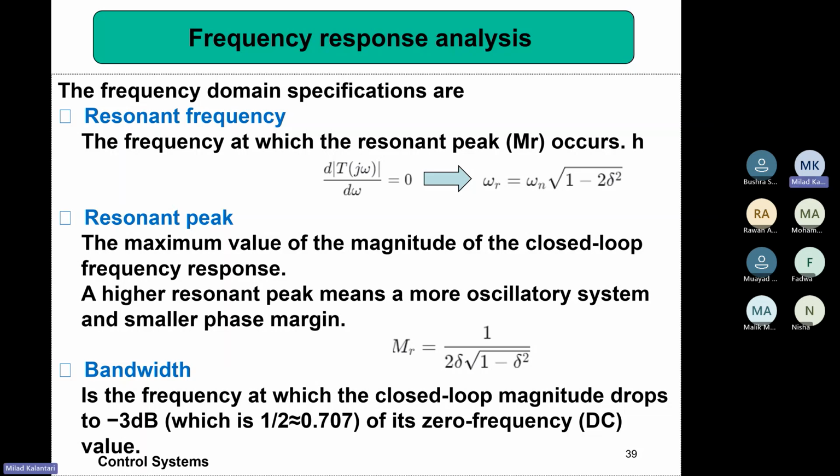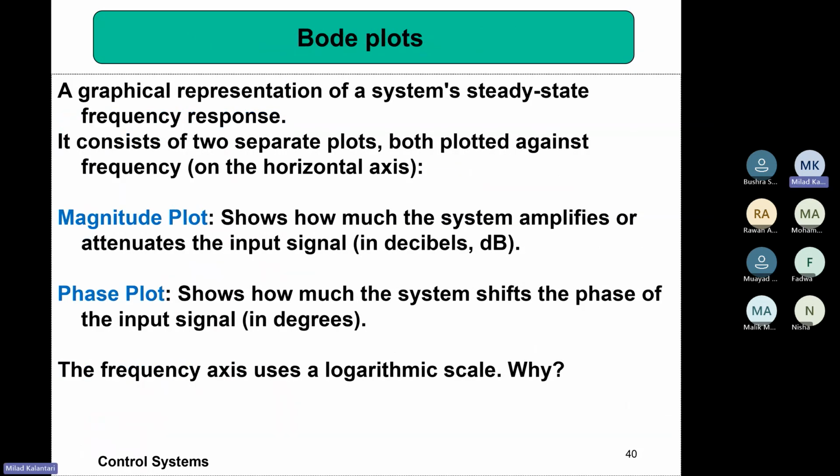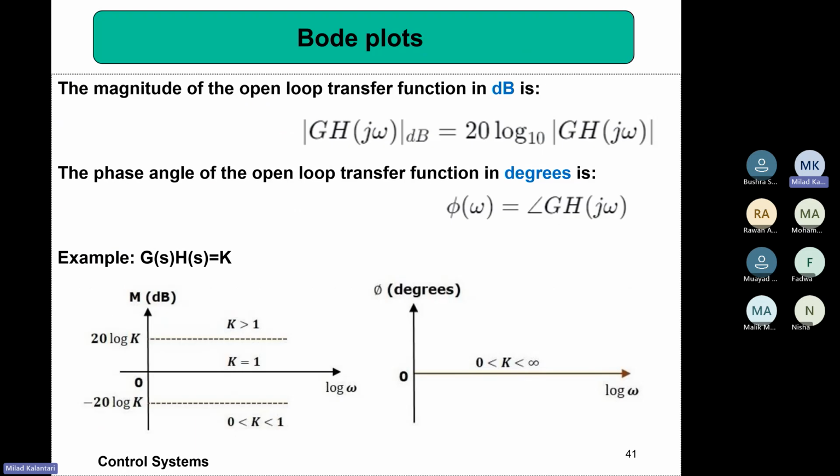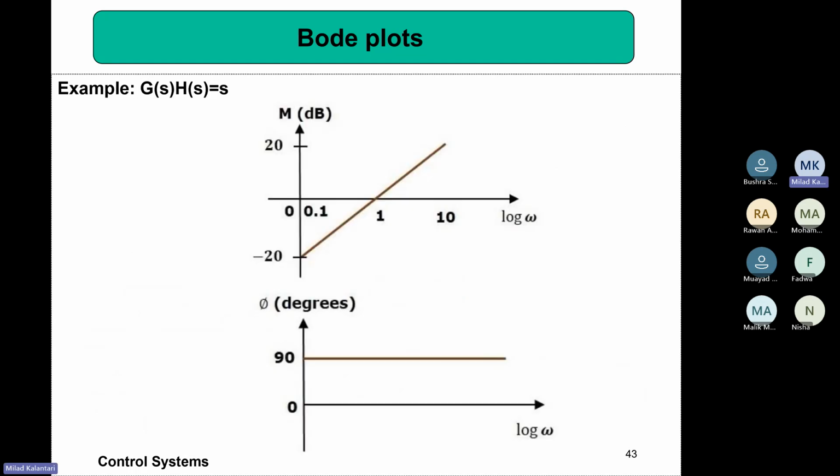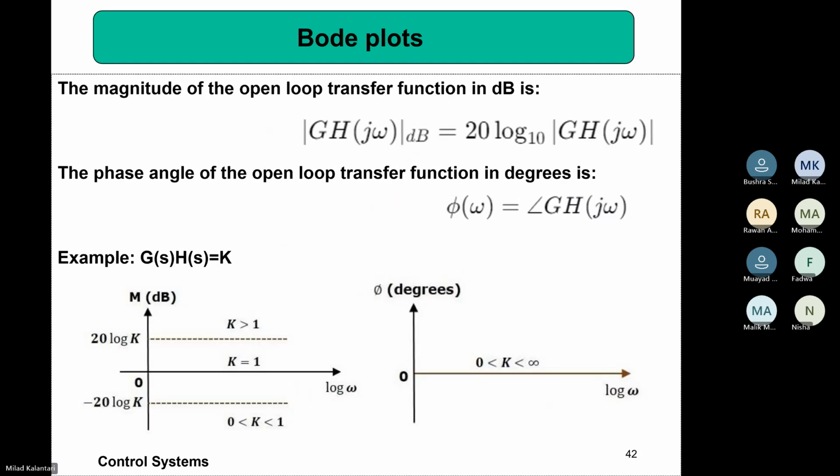But we need to know how we are going to use this as the criteria for stability. First of all, we need to know how to plot this, right? To plot, we go from the low frequency and then try to estimate the behavior at the higher frequencies, and then the behavior at the region of the pole, both amplitude and phase. And then how we can use this for finding the stability problem in our case. Basically, we want this to understand the stability.